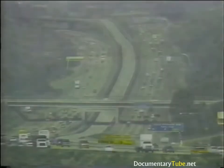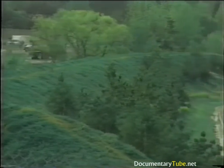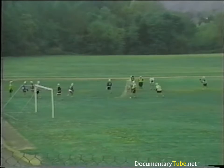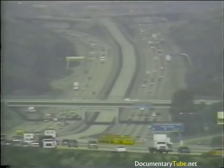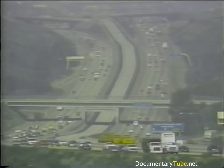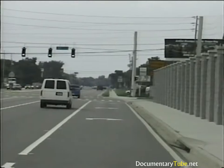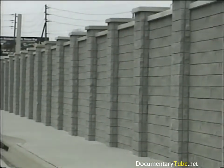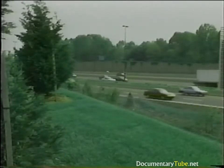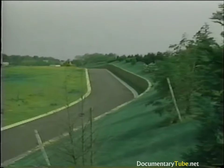Natural terrain features, such as hills and dense woods, as well as man-made features, such as buildings and walls, obstruct the sound path between source and receiver, and in most cases reduce or attenuate noise levels for nearby receivers. The amount of attenuation provided by these objects depends on the size of the object and frequency content of the associated noise source. The term noise barrier refers to any large object that blocks the line of sight between source and receiver, including the ground itself if it protrudes upward through the line of sight. A noise barrier is commonly a wall or earth berm specifically constructed for the purpose of noise reduction.